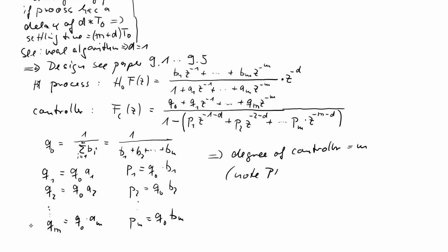Note the PID always has m is 2. Yeah? There is just a constant degree of any controller for any process. If you use a PID, you have just here three multiplications. Here you have more multiplications. So the controller for higher order systems needs more computation power of your microprocessor. But you see, the design is simple. You can do this before you run your controller or during runtime. That doesn't matter. This controller is called deadbeat controller, and we should do, I think, a first example.